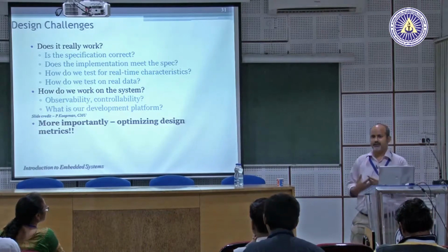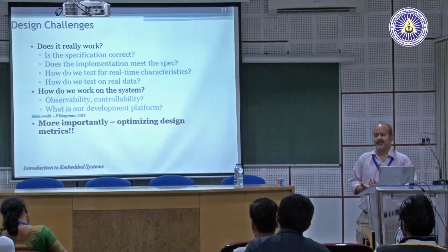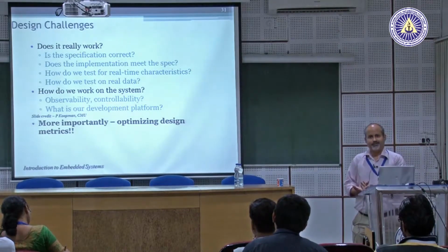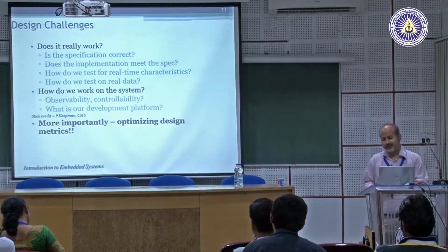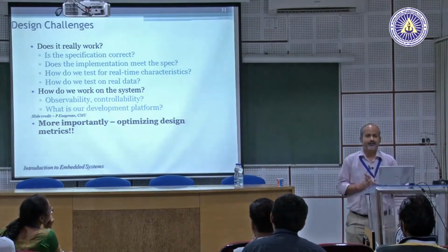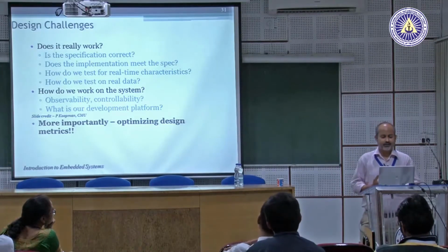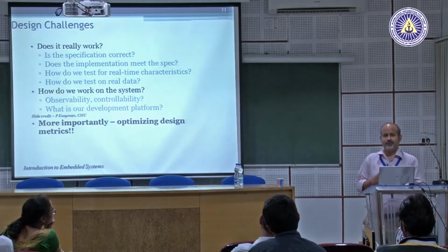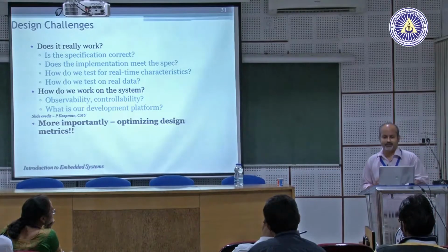You cannot observe your system to its fullest. If you lose observability, you cannot control the system because you don't know the state of the system. So when you design your sensor interfaces and choose your sensors, how do you make sure that your system is always going to be observable? How much redundancy do you have to put into the system?